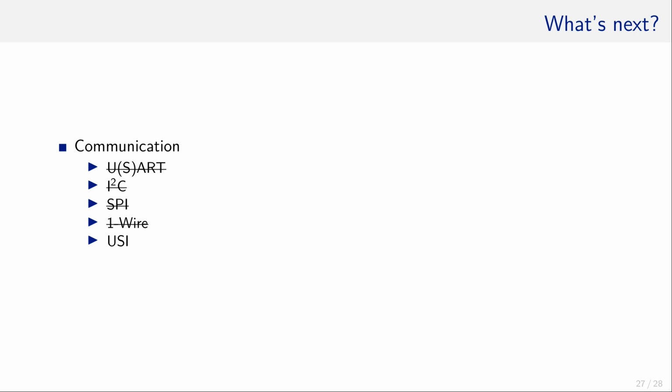In the exercise, we will have to implement the DHT protocol by bit-banging a pin to a DHT humidity and temperature sensor. You can use one if you have one. If you do not have one, you can use a second Arduino and flash the provided DHT program. It will behave like a DHT sensor and reports the temperature. More about how to report a temperature without a temperature sensor in the ADC chapter. For now, please head over to the exercise.